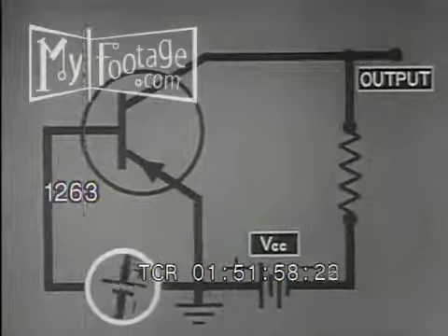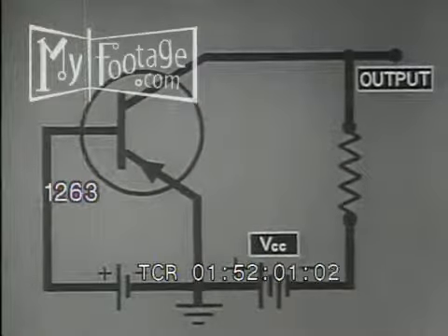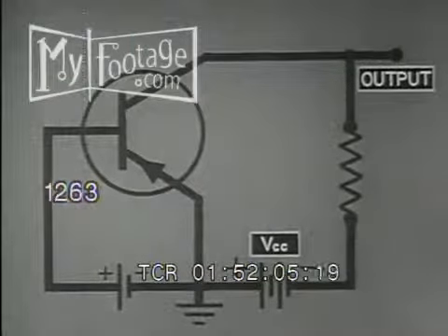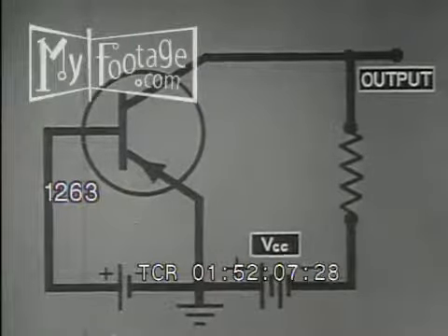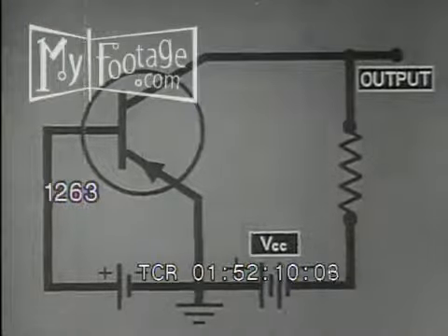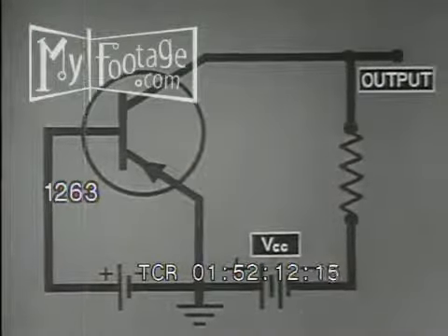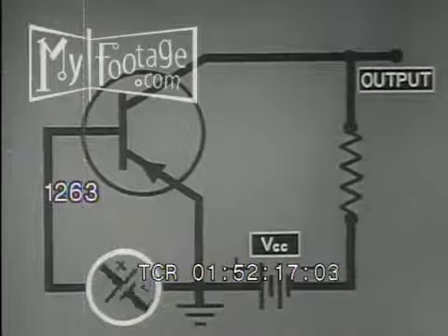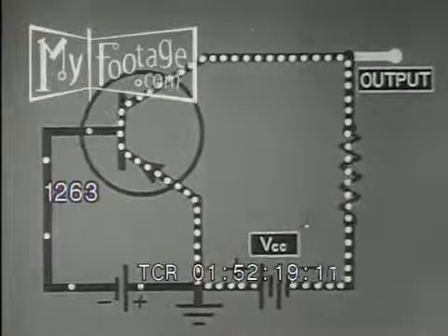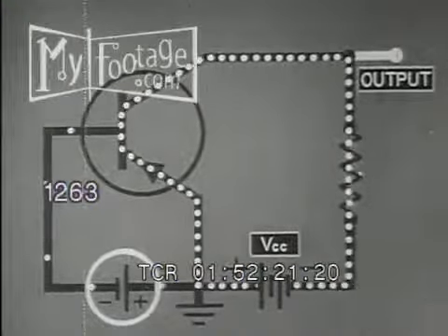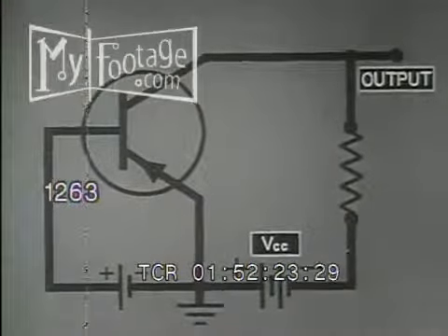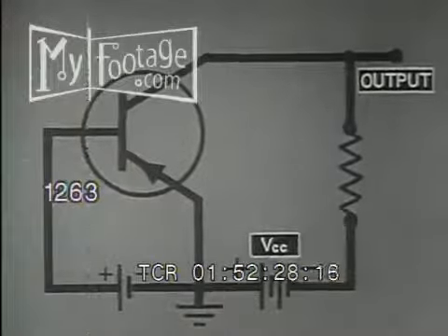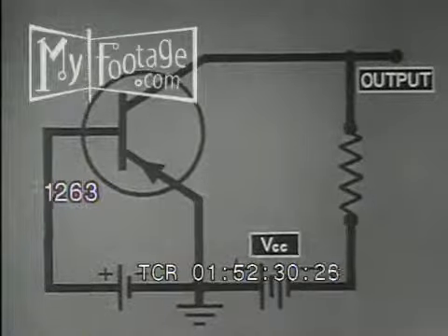When the switch is off, there's reverse bias on the emitter junction, and without forward emitter current, no current can flow through the collector. With no current, no power is consumed. So, whether the circuit is on or off, there's no power loss. It's practically a loss-free switch, as efficient as a knife switch.